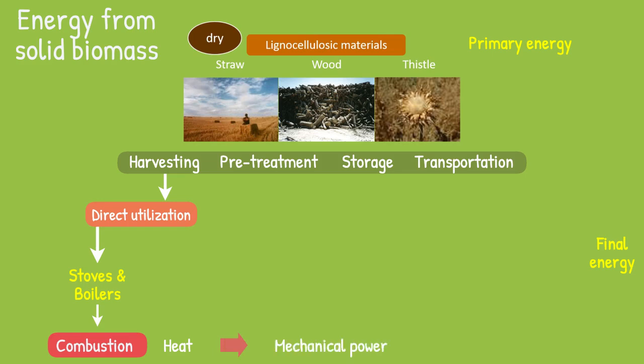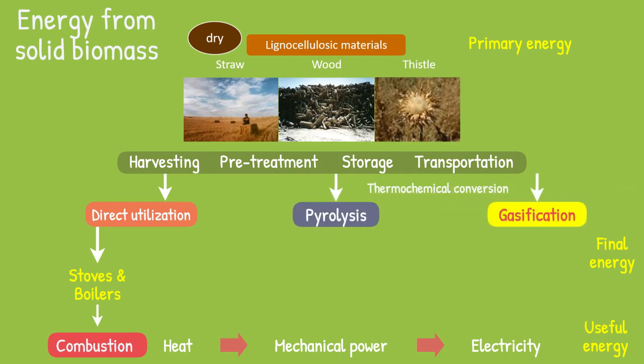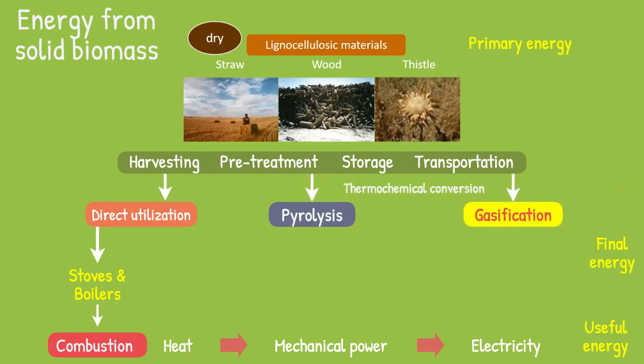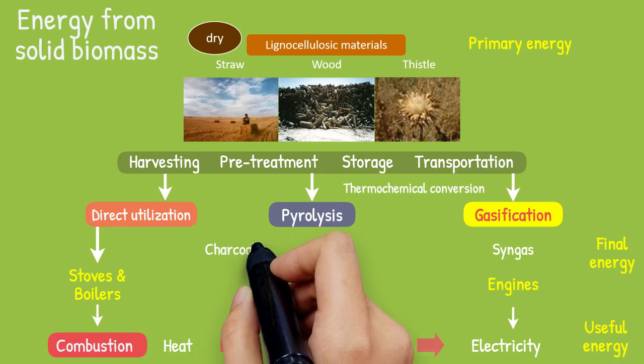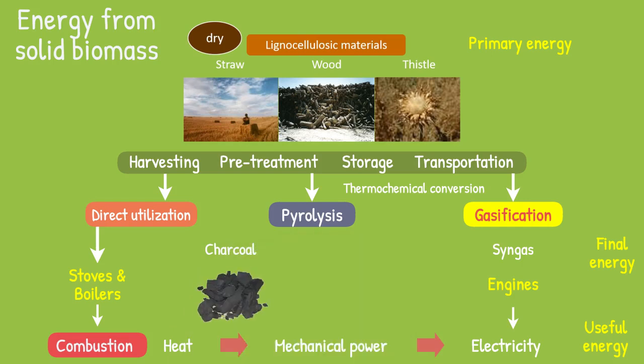For the production of electricity, we will study conventional systems with the Rankine cycle. Pyrolysis and gasification are also included. Gasification is a technology in the pre-commercial phase for the production of electricity. Conventional pyrolysis mainly produces charcoal. Fast pyrolysis is a technology under development, which is aimed at the production of bio-oil. Bio-oil can be used also in internal combustion engines to produce electricity. The synthesis gas produced by pyrolysis is used to provide energy to the endothermic pyrolysis process itself.